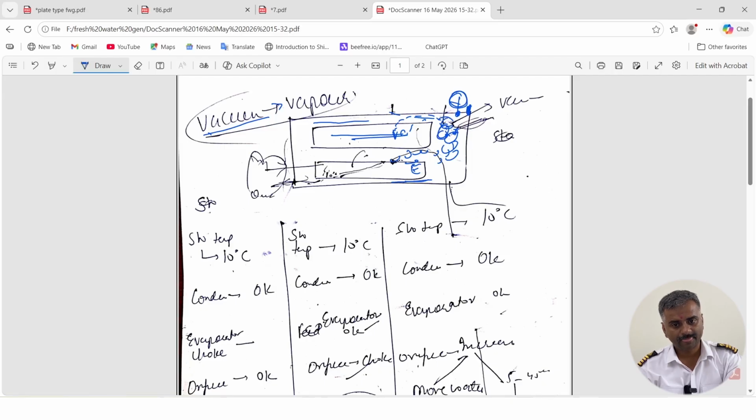Why? Because there is something obstructing the vacuum, right? If it is air or vapor or anything which is present, it will cause the vacuum to reduce. So if your vacuum was initially 90% and your condenser is not able to condense, it will fall down to 80%. And so will the casing temperature, because the steam is present inside. So the shell temperature will start rising, 40 to 45 to 50 degrees centigrade. That means the steam produced is not able to condense. So that is the funda.